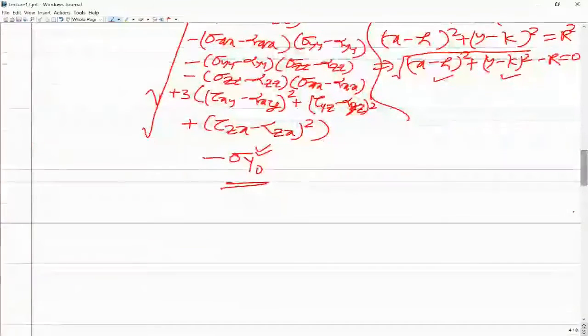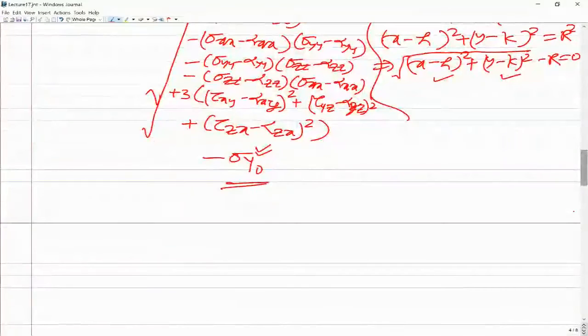So now to get the tangent constitutive matrix, you need del f by del sigma, you need del f by del alpha. And also you need the Prager's constant, because when we talk of the evolution of back stress alpha, we need the Prager's constant, the simplest model. So I will show you how to get del f by del sigma, how to get del f by del alpha, and how to get the Prager's constant C for this case.